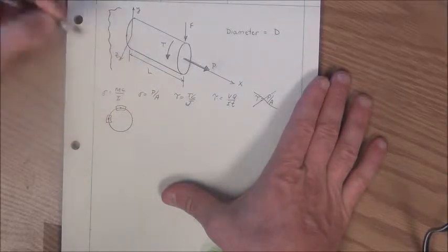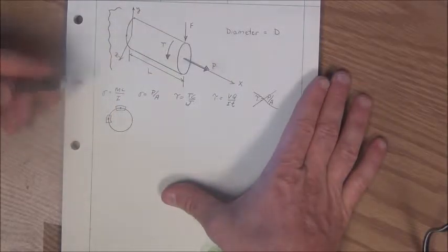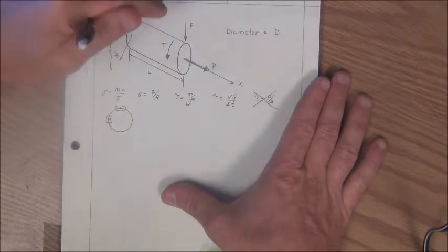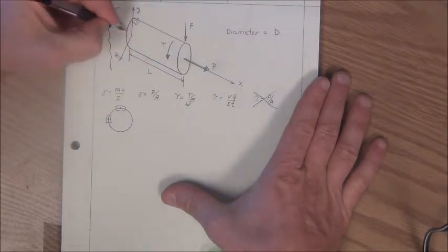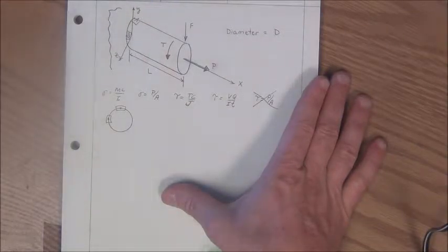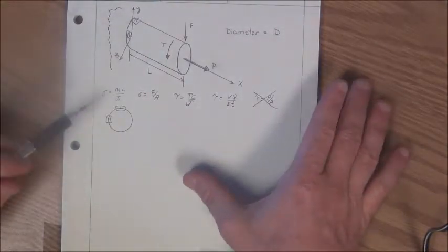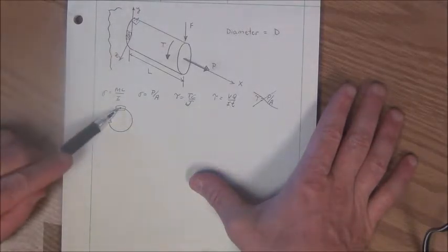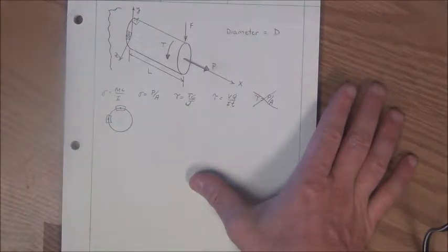These are infinitesimally small elements, but I will draw them as finite-sized elements to allow me to clearly describe the stresses. So if I were to draw these elements back here on my structure, I would have element A wrapping over the top of the beam, and I would have element B here on the side of the beam. I've defined the locations where I want to know the stresses, and I'm ready to start to solve the problem.